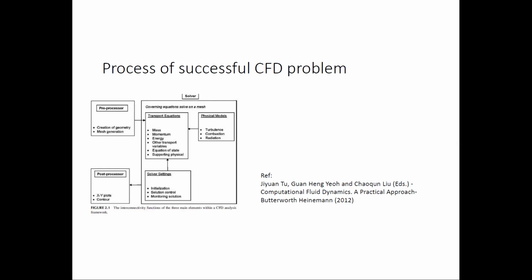these equations that we are going to solve, there will be a closure problem. The number of unknowns is greater than the number of equations for the solution. So we need a closure for this problem using a physical model. For example, we have turbulence models, combustion models, and radiation models. By this way, we can define a set of equations where the number of unknowns is close to the number of equations, or the degrees of freedom. So the problem will be deterministic, not an undetermined matrix.